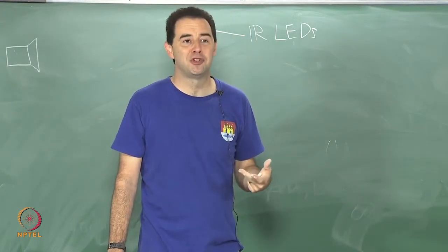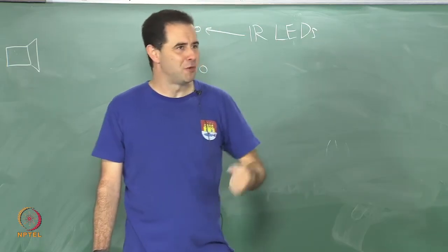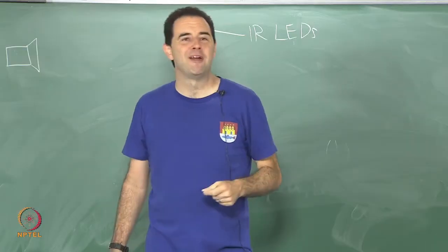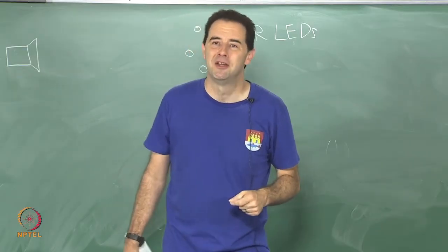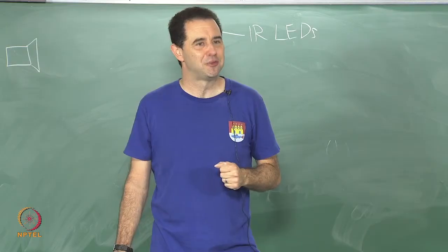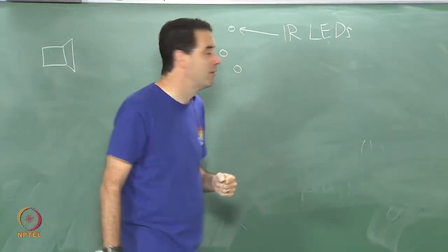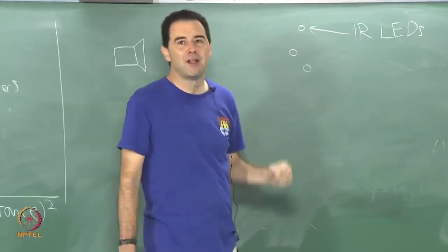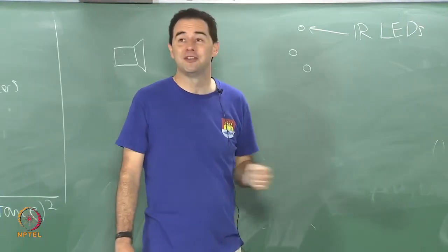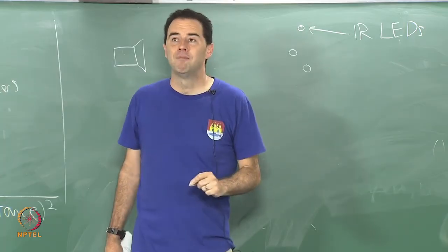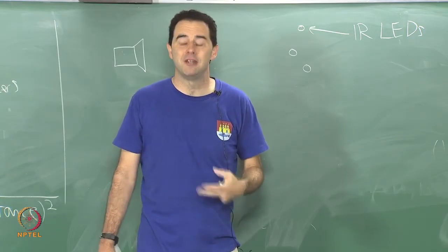So in terms of computer vision, real computer vision, if you want to make something powerful, you should be using natural features. If you put the features in the environment yourself as special markers that you've painted, you've cheated, right? You're helping the vision out, so that's fine. That gives much better performance, but not as impressive from a pure computer vision standpoint. You want to go even further, put some bright lights in the environment, bright and infrared in this case, and then just track those. And if they're small, very well separated, you get these points or these features that we need to get to the next level.